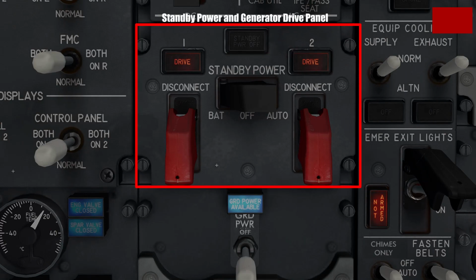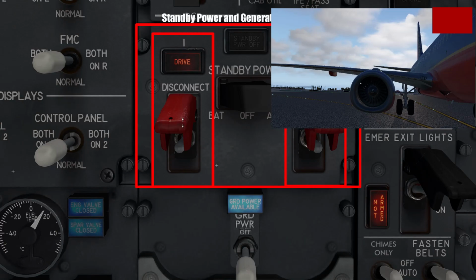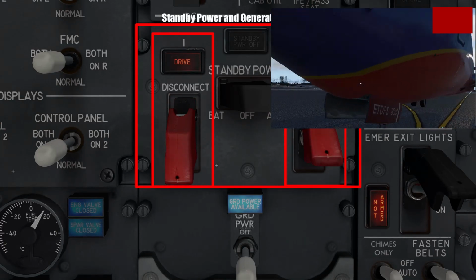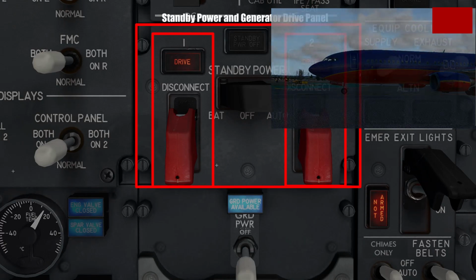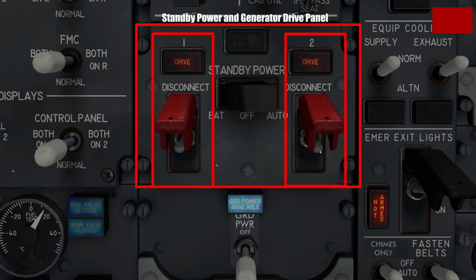On either side of this system are two red guarded covers, which are the engine electrical generator switches. During normal operation of the aircraft, the electricity is generated by the motion of the fan blades of the engines, sort of like a very fast windmill, which drives these generators. However, in the unlikely event that one of these generators experiences a problem, the pilots can manually flip the covers and disconnect the generators. Note that this is a permanent disconnection, and it physically prohibits the engine's turbines from acting as a power generation source for the aircraft.